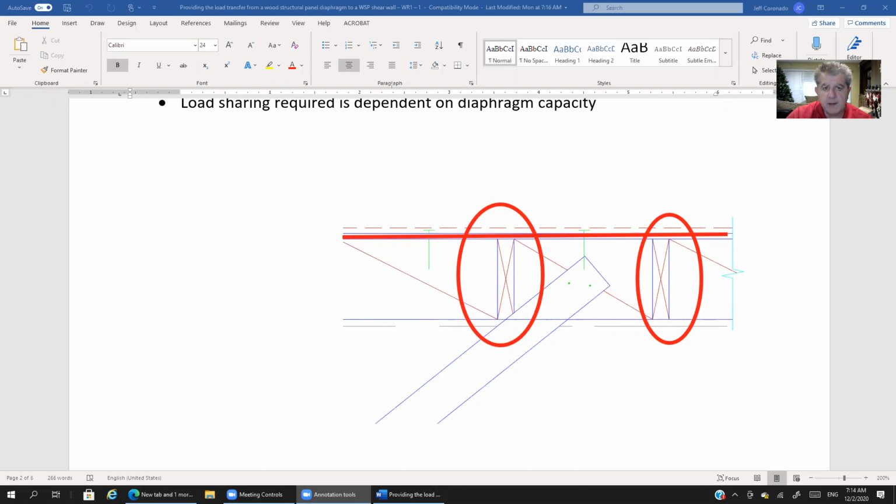What else do we have here? We have some blocks, right? And I believe I already said this is covered in other sessions in Bridging the Gap. And here is our diagonal brace. Now, what might be harder to see is we have nails here that are connecting the brace to the block. So we want to connect the brace to the block with nails.